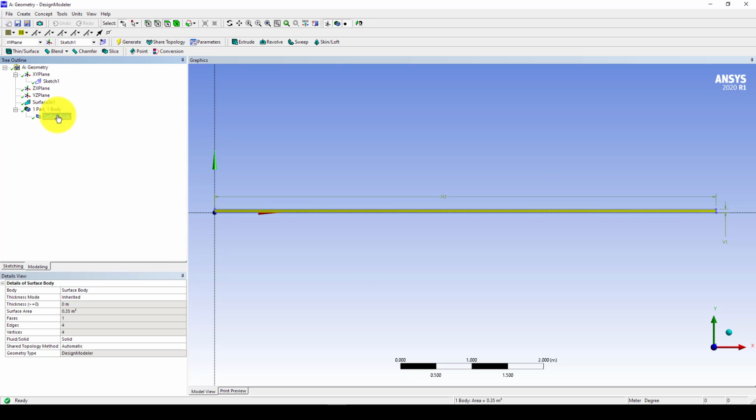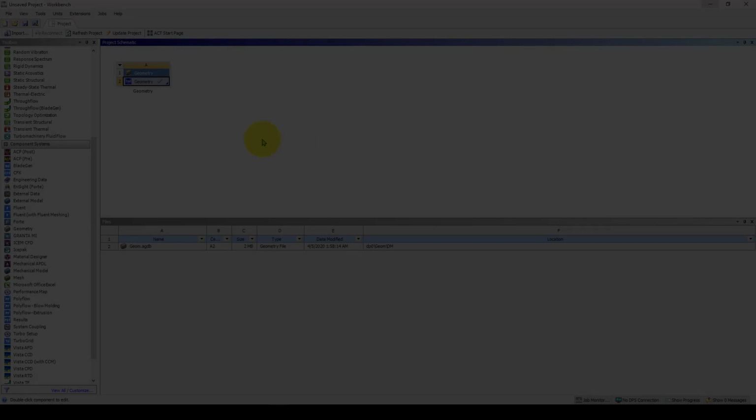So we need to have the surface. Now select here. Again, you can change the name. You have several options there, but I will choose just Fluent. This is not compulsory, but since we're going to move to Fluent, it's a good idea to have it. Remember, for every option here you always need to press generate, as we did previously.